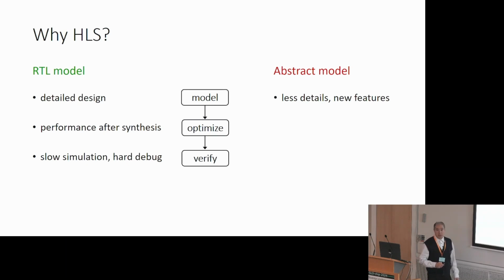Considering optimization, we can rely on the tool that performs assessment of the designed, of the synthesized circuit based on a characterized library. So the input to the tool is not only the C code, it's also the characterized target library, either FPGA or ASIC.